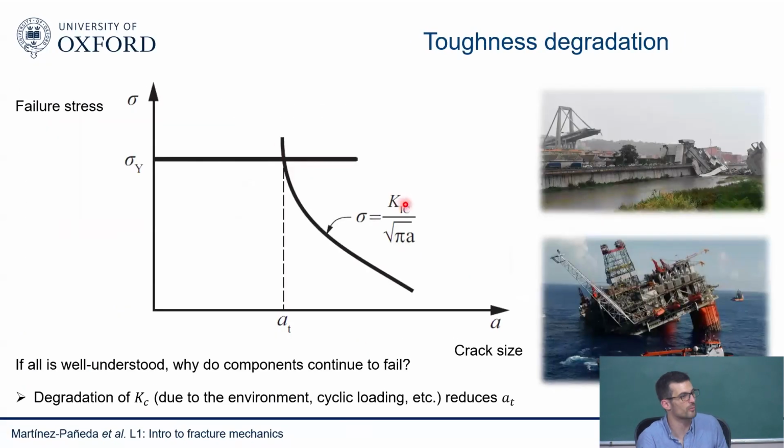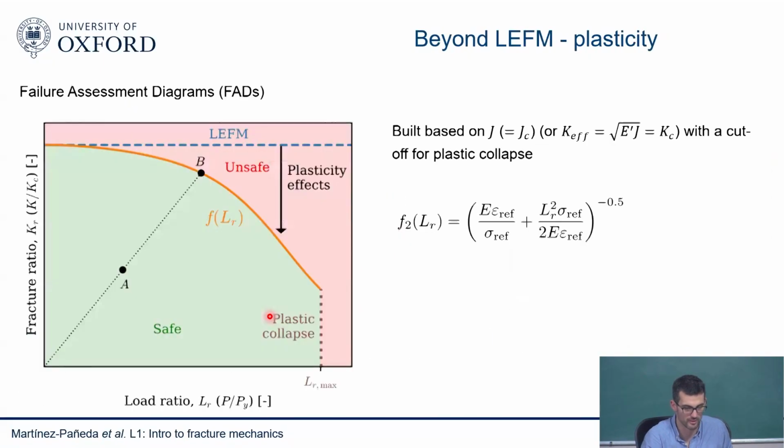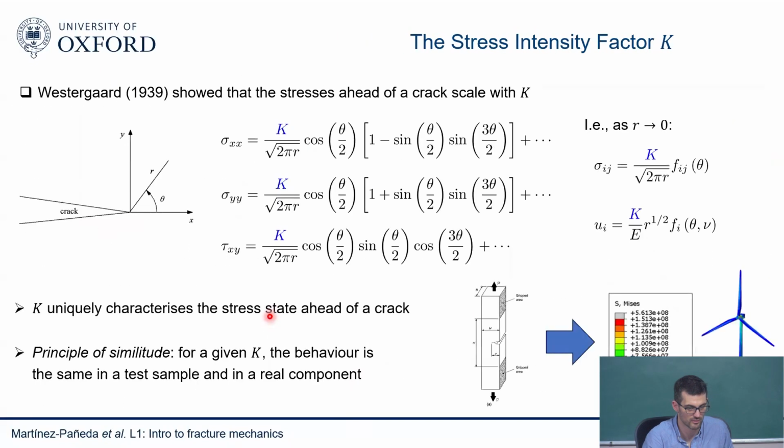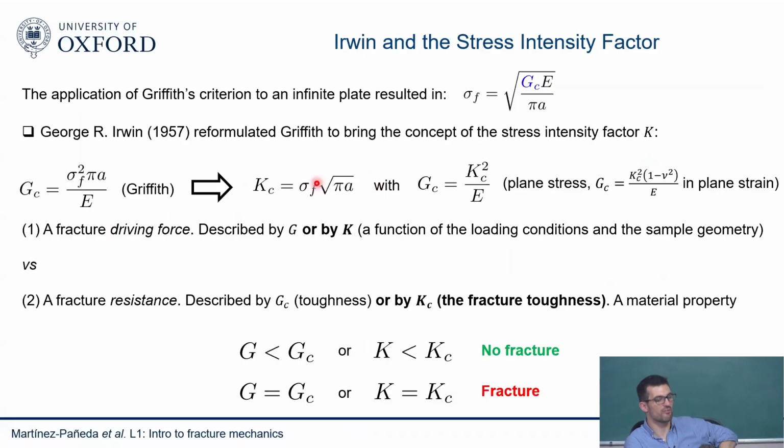So here, from your toughness of the material, you know that whenever you reach, or maybe even simpler, right? Here, if I know my toughness and I know, let's say, that aircraft wing is going to be exposed to a pressure of, maybe if we think of an aircraft component inside the plane, basically every time you fly, you increase the pressure, you lower the pressure. So it's a pressure of whatever, 400 megapascals, whatever it is. Then you can solve for your critical crack size depending on the toughness of your material. You know the toughness, you did an experiment. So let's say that your critical crack size of this metal, an aluminum component that you use, might be 6 millimeters. Okay, so you have 1 millimeter to start with, and when it reaches 6, it will crack.